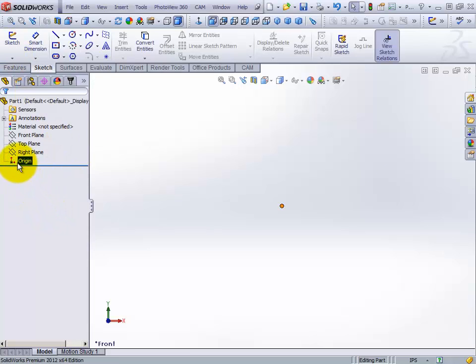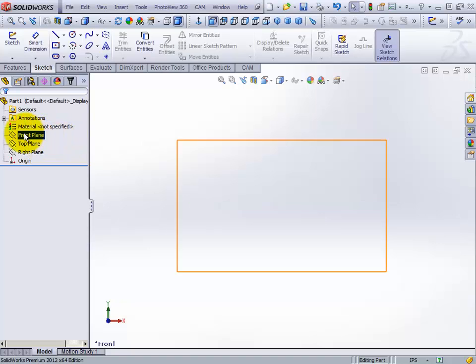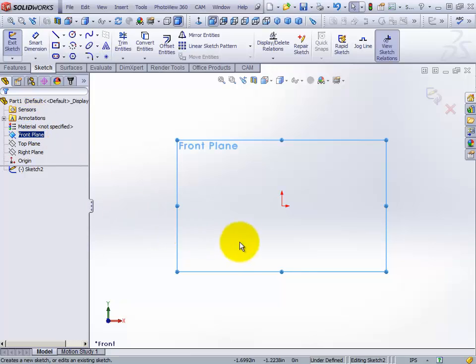So let's repeat what we did earlier. You can just come right into this, click left, click the pencil, and remember there's that orange dot meaning the middle of the origin, 0, 0, 0. But also notice that there's an asterisk. That asterisk means a point. In our system, that's a point. If I go up to here and hover over that, it says point. Well, in this case, it's telling you SolidWorks has already drawn a point for you. It's called the origin.